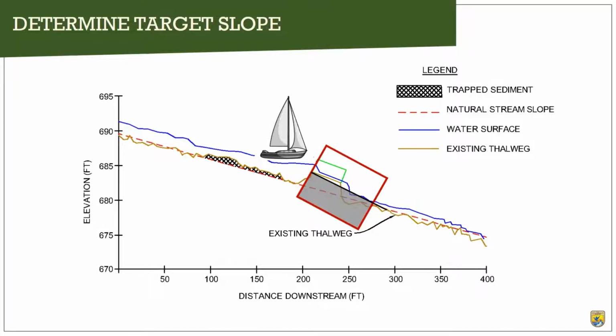But we might be in the situation where we are at a lake outlet with recreational uses upstream that need to be maintained. People might have docks or floatplanes or whatever. In Alaska, it's pretty common. And then we're going to need a steeper crossing, which means we're going to need a steeper geomorphic analog to design that crossing.